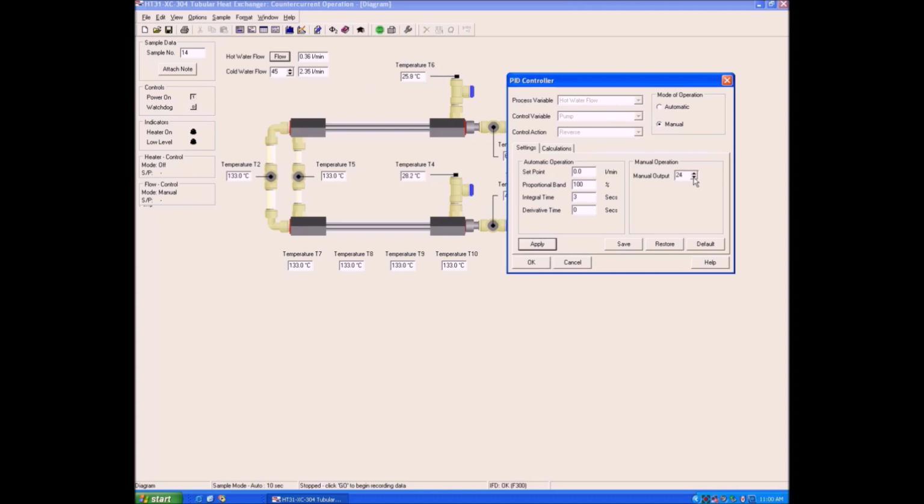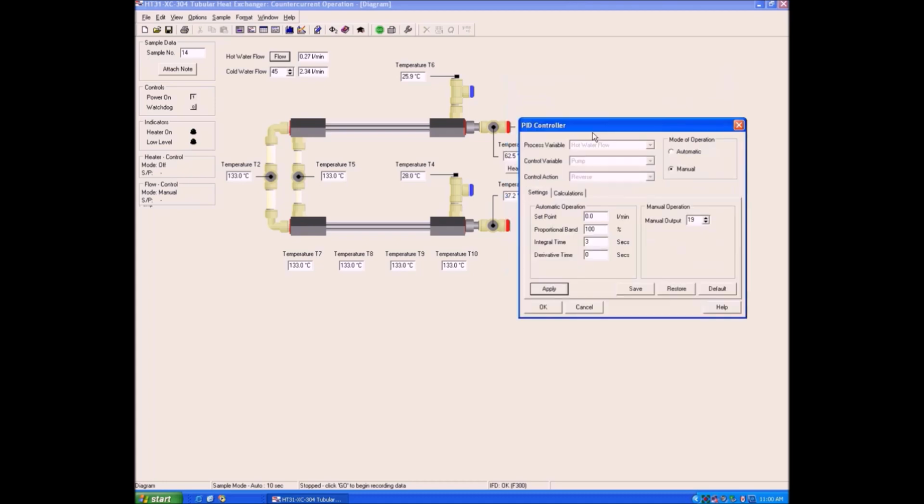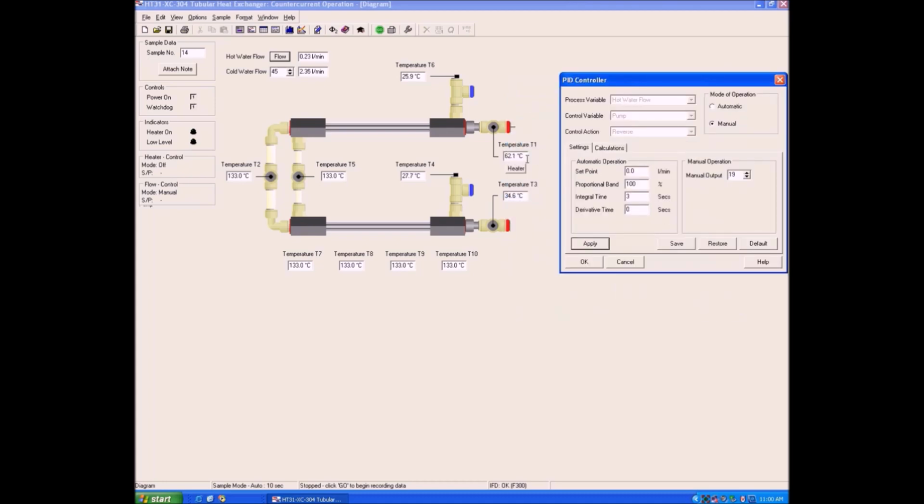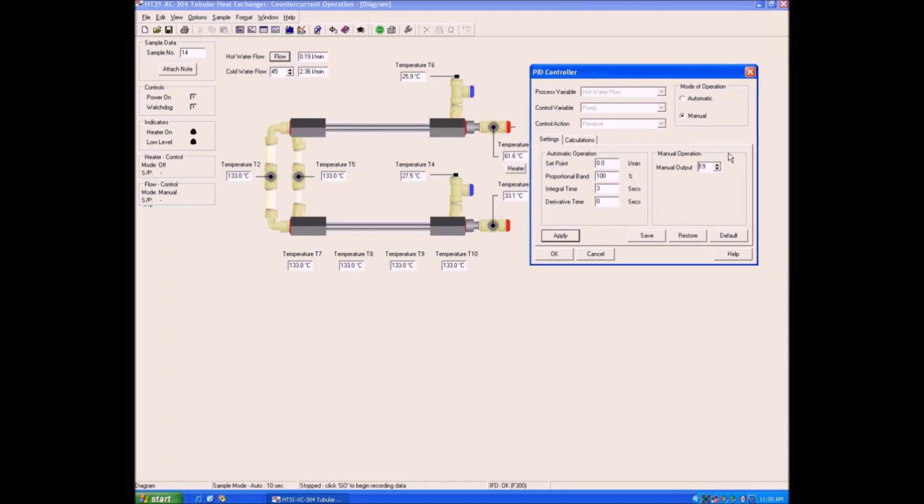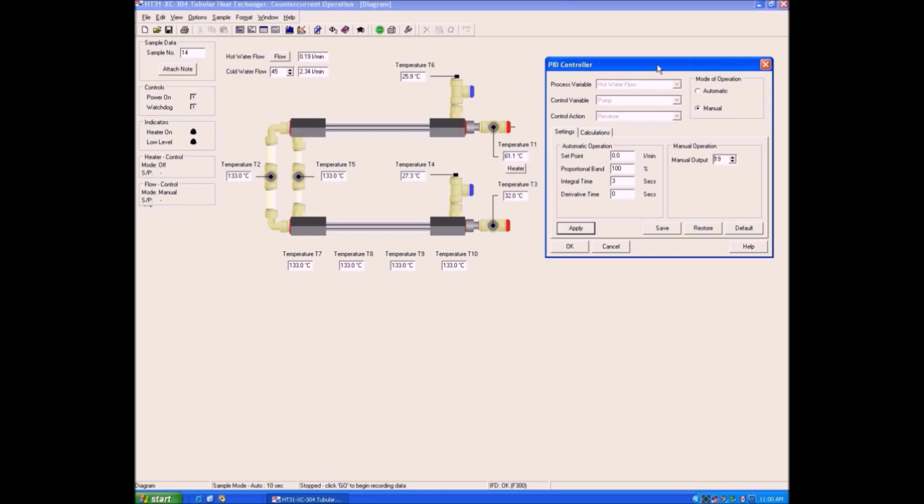Flow rate is 58. Now we can decrease this flow rate slowly to 0 and turn off the water flow. The temperature is 62, so let it cool slowly for safety. We need to decrease the water flow rate slowly, otherwise the water remains heated.